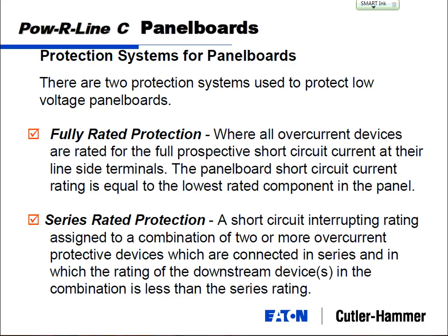We've got a couple of different breakers here I was going to show. In the running and receptacle panels, for 208 volts, we've got a standard interrupting rating. The minimum is 10,000 amps, or 10 kAIC. So these breakers here, 1 pole, 2 pole, 3 pole, are circuit breakers designed to withstand 10,000 amps fault current.